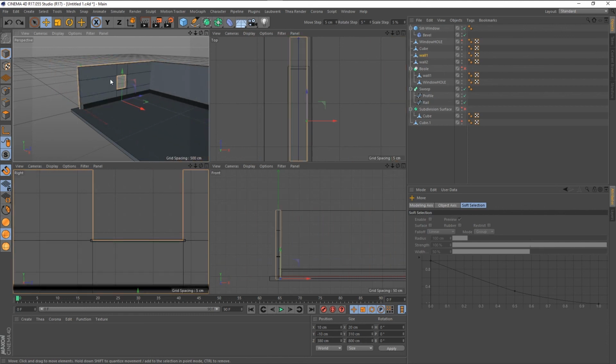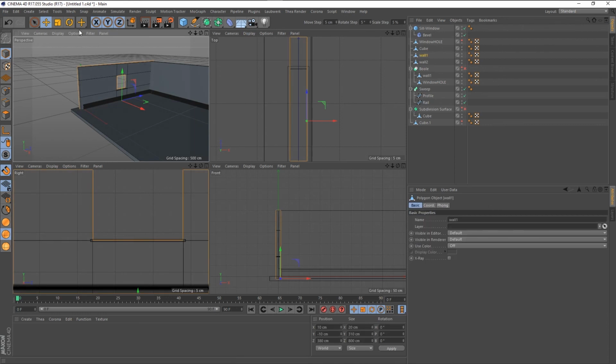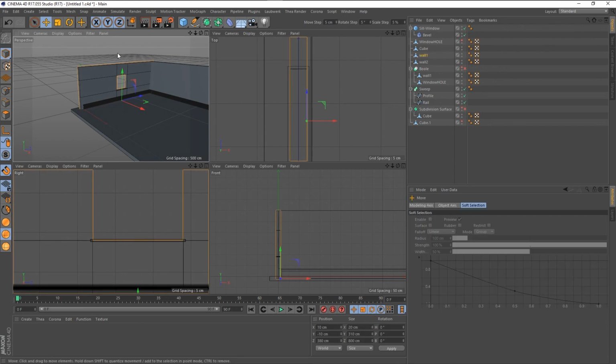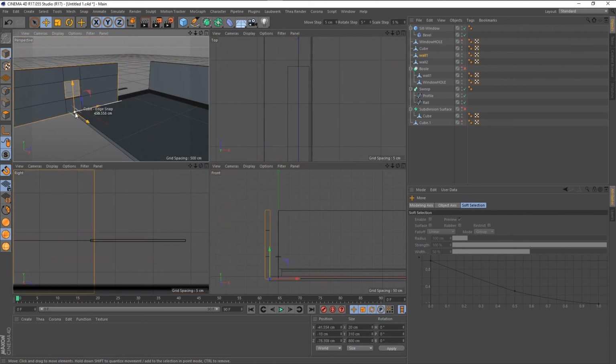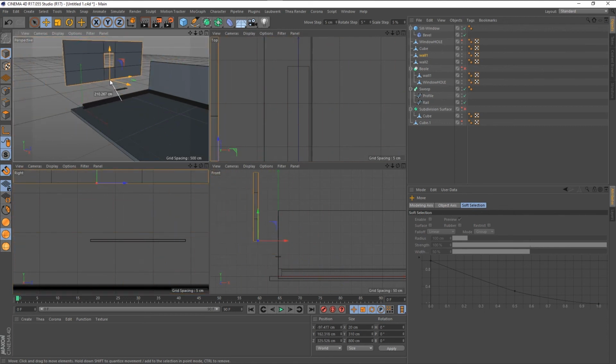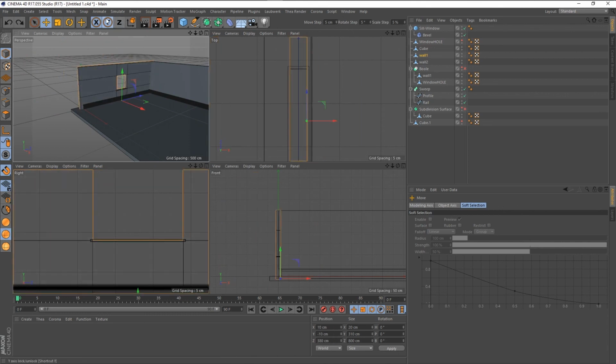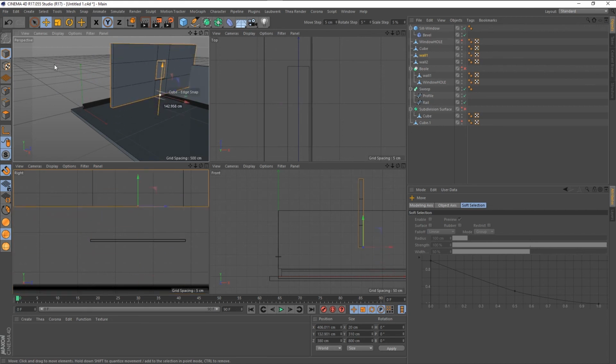Okay. So first you select your object. If I use the move tool or hit E for move and I drag, it's going to drag in reference to my perspective view. Control Z. But if I disable those two, it'll only move according to the X, and I don't have to touch the X gizmo. I can just click and drag and it's going to move on the X. So that's what these locks are for. Now I can click and drag and it moves on the Y.